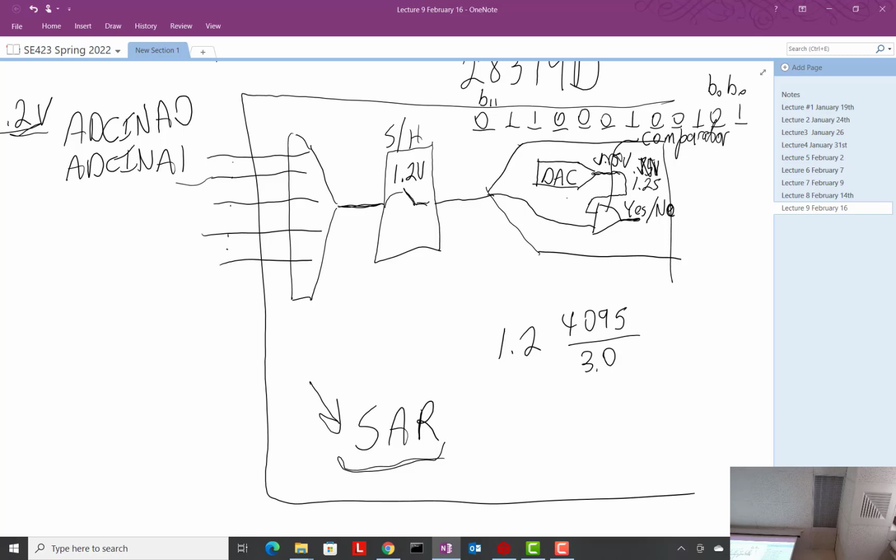You can tell the ADC to convert, and then you can sit and watch a register bit to say when it's done. There's usually a busy bit. And you could read that busy bit. Are you busy? Are you busy? Busy means you're still converting. And when it finally is not busy, then you could go read the results register. But because that takes microseconds, you're wasting a lot of processing time. You should be doing other things during that.